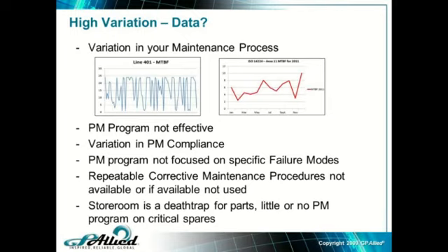Storeroom, I talked about this earlier, death trap for parts. And a lot of times I see little or no PM on critical spares. I know this may surprise you, but I have been in plants where I go into the storeroom and none of the electric motors, especially the critical ones, have never been rotated. They're supposed to be rotated every 30 days, 1 1/4 turns. And they say, well, I don't have the maintenance people to do it. If you got someone in the storeroom, a PM could be sent to them saying, rotate shaft 1 1/4 turn on this motor. Not a problem.